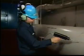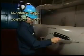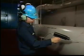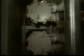The leak detection methods we will use include general scanning mode procedures using the contact probe, pressure, vacuum, and tone methods. In an online environment with equipment under pressure or in a vacuum condition, a leak will move from the high pressure side to the low pressure side, generating a turbulent flow with strong ultrasonic components. These sounds are detected with the ultraprobe using the scanning or contact mode.